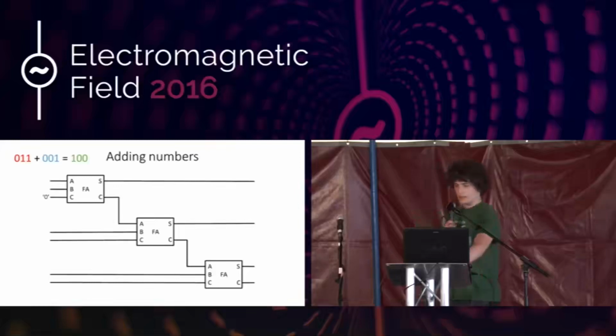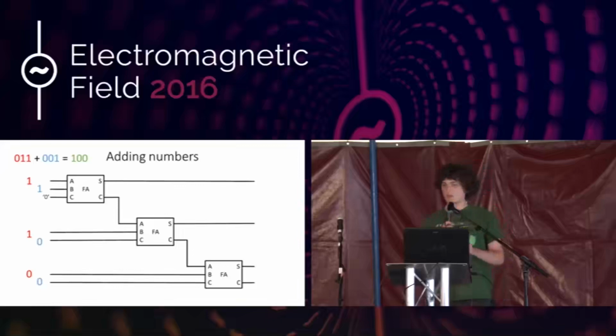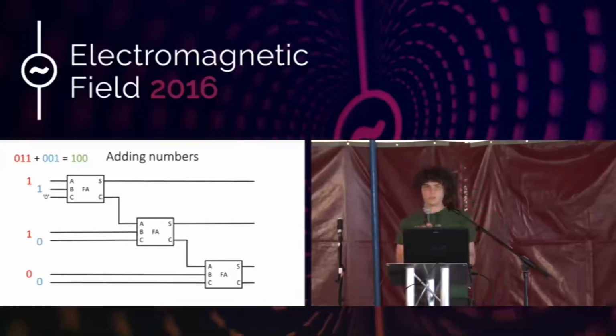What we do is we connect the signals or these numbers to the adder as on the slide. So to each one of the full adders, we connect a corresponding bit of the number that we want to add. So then we see for the first adder, we're adding 2 1s and a 0 because it's a fixed 0, it's the first number. So the result should be 2 in decimal or 1 0 in binary. So the sum should be 0 and the carry should be 1.